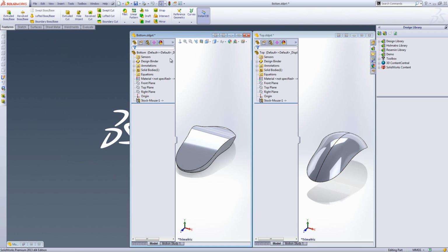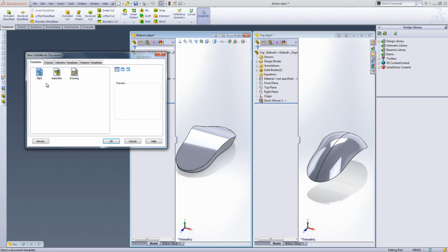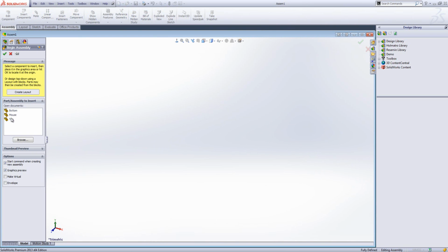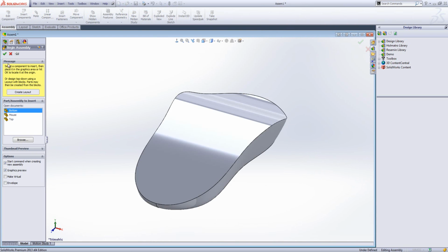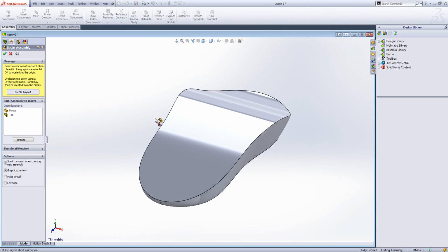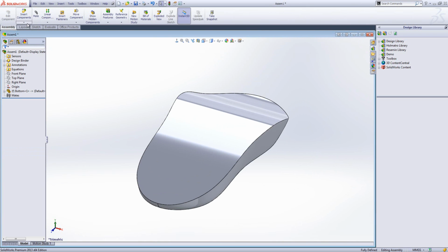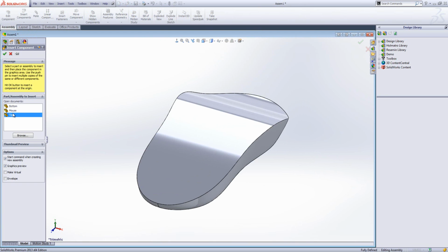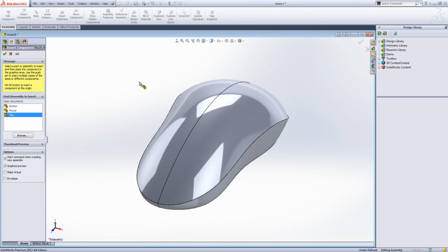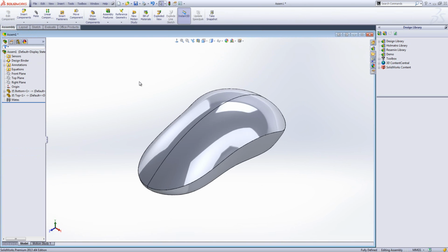Now once you've done that work, if you want to create an assembly using those parts, what's quite nice here is because they've been defined within one part, what you can do is you can just tie their location to the origin location of the assembly, and they should line up perfectly for us.